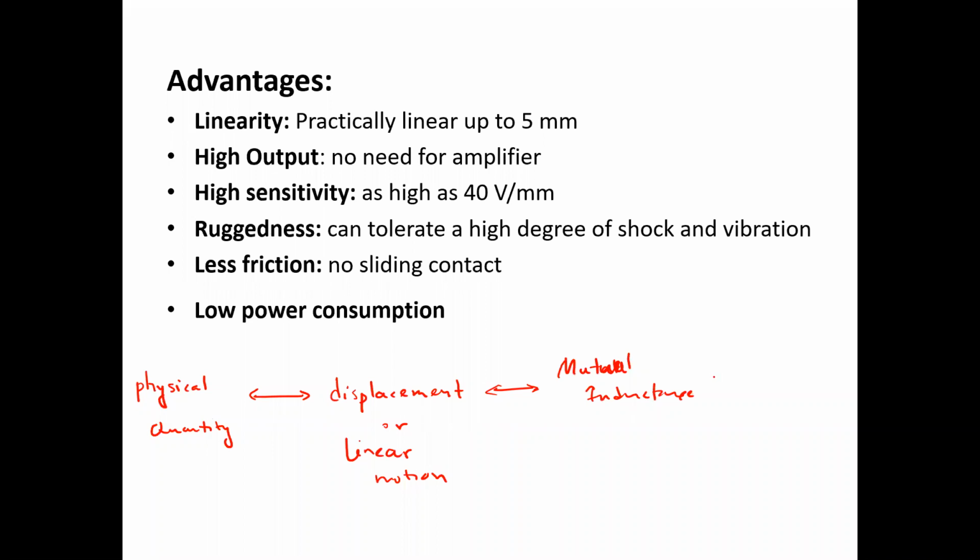And as the mutual inductance is changing, and as we are taking the differential output, the final form of the energy that we get is the voltage difference, or differential voltage. So for measuring any change in any physical quantity, this sort of energy conversion will normally take place in the case of LVDT. Now these two portions are actually taking place in the LVDT.